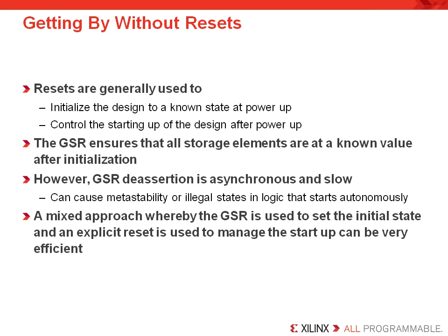In general, a mixed approach whereby the GSR is used to set the initialization state and an explicit reset is used to manage the startup on some components can be very efficient, and that's what most designers actually do. They'll take those few components they need to reset and make sure they're in a known state to begin with, and they might go ahead and either use the GSR for that, or else they might do a secondary reset after configuration to reset the component.